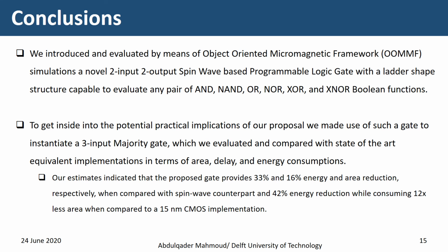In conclusion, we introduced and evaluated by means of object-oriented micromagnetic framework simulations a novel 2-input 2-output spin wave based programmable logic gate with a ladder-shaped structure, capable of evaluating any pair of AND, NAND, or NOR, XOR, and XNOR Boolean functions. To get insight into potential practical implications of our proposal, we made use of such a gate to instantiate a 3-input majority gate, which we evaluated and compared with the state-of-the-art equivalent implementations in terms of area, delay, and energy consumption.